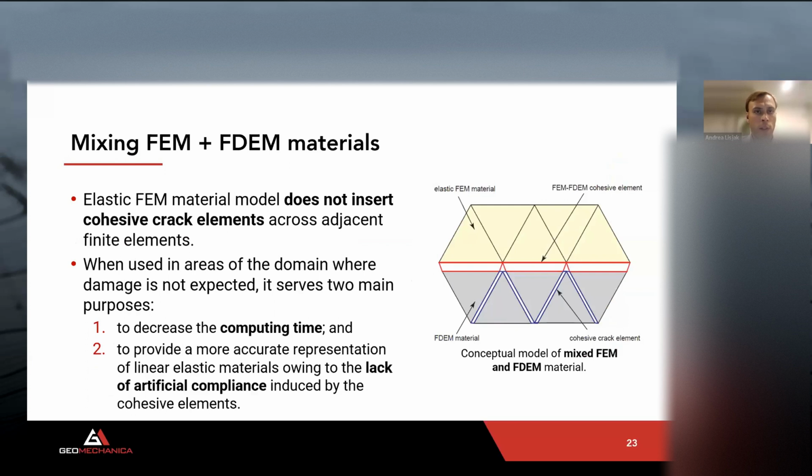Another important feature that was recently added is the ability to mix FEM and FDEM material models. Before, your whole model would be an FDEM model, where you would have cohesive crack elements interspersed everywhere in the model. These elements are important to model fracturing, but often there are areas where fracturing does not occur. So now you can assign a FEM, a continuum model, to those areas. The main advantage of this is a drastic decrease in computing time.